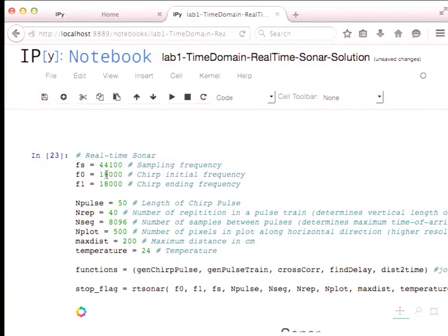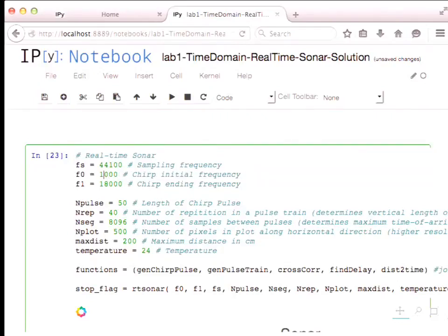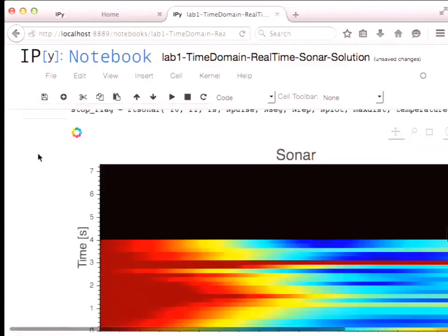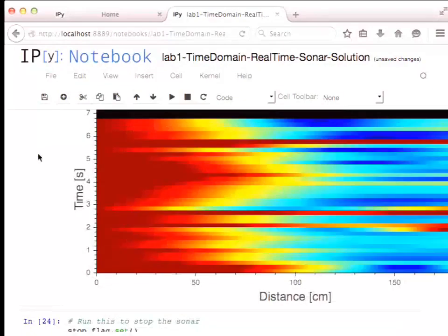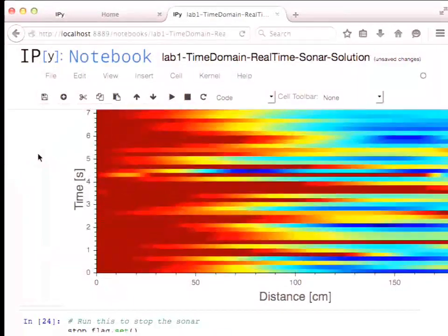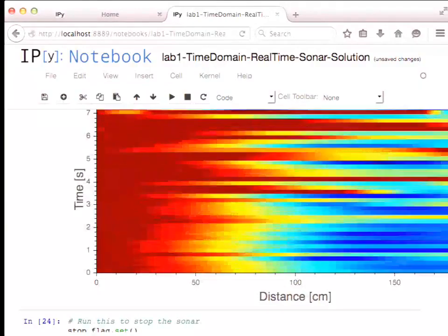So now the resolution wasn't good. I'm using a 50 length pulse. What I'm going to do now is make it a chirp, so it has pulse compression, and I'm going to actually increase the pulse. So what happens if I keep this at 10 kilohertz, so you can actually hear it, and then I make it into a 500 length pulse? Hear it? I lost resolution because I made it 500. You see, it's not very good. So now I really lost my resolution.